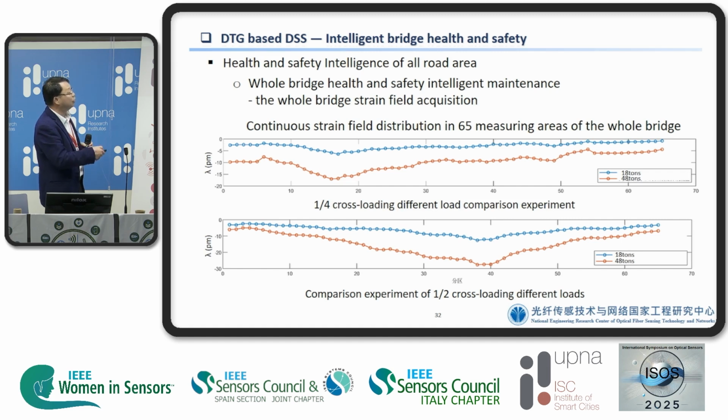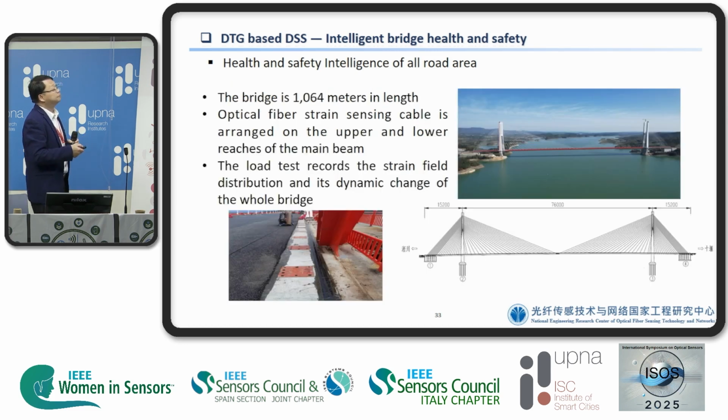Normally monitoring by the shift of the wavelengths. Then with the time schedule, you see what happens. For example, if we have the loading at different areas, in these areas you can see the deformation here, and in these areas you have the deformation there. So this is typically for the bridge monitoring, especially here in China.